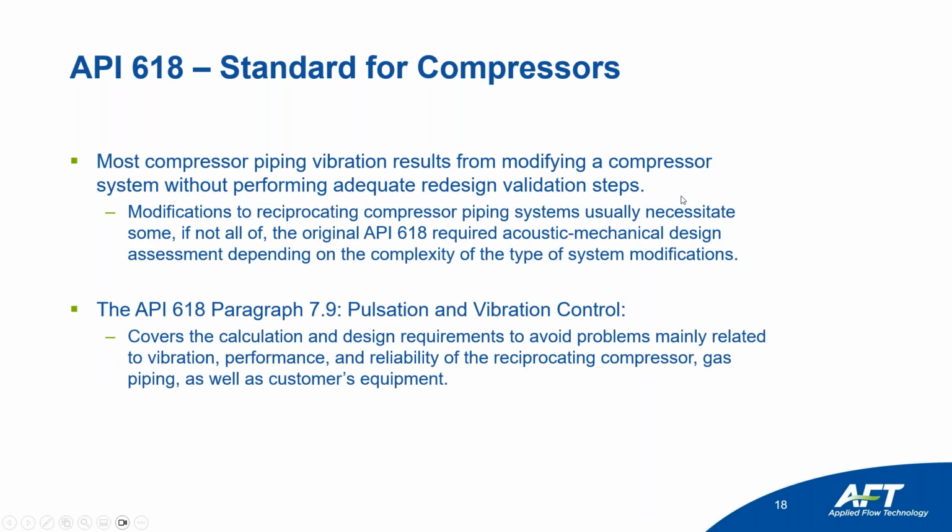Because the performance of a reciprocating compressor is a combination of system dynamics and compressor design, changing the design of the compressor or the design of the system without any modeling is risky. Careless redesigns may lead to unanticipated vibrations, necessitating mitigation and future redesigns. The portion of API that we're concerned with is the section on analyzing pulsation and vibration control, this section 7.9, which dramatically affects compressor and system reliability and performance. We don't model compliance with every single aspect of API 618, which gets a lot into the compressor design itself. We're only focused on what can be simulated with xStream.